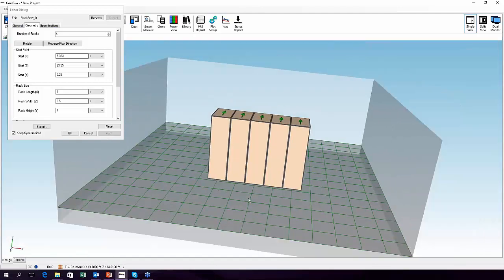But remember, I've just increased the density of the mesh because now my minimum mesh threshold is going to be at least 3 inches, probably less because I need 2 cells in there to make it work. So it's probably going to be 1.5 inches. And that drives up the mesh count, drives up the solve time, and drives up the complexity. But you can do it.